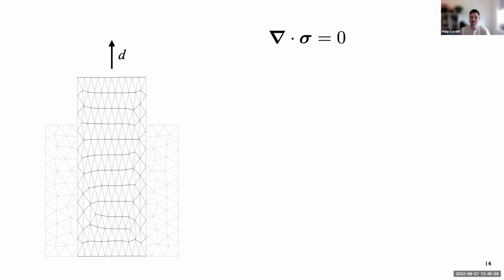Conceptually, if we take this quasi-static approach, ignoring inertia and body forces, then the divergence of stress is zero. You can think of this as summing the force around any element or set of elements, and that has to equal zero. The force is the area vector in an inner product with the stress tensor, so area by stress gives you your force.